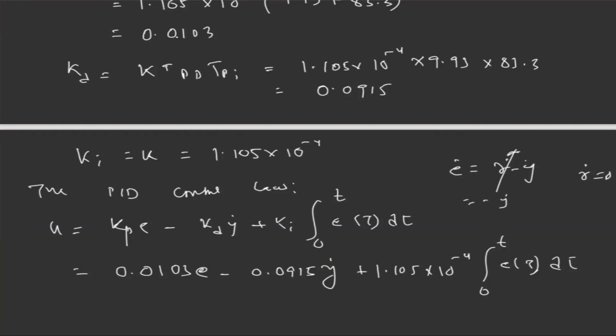So this is how we can design the PID control for the aircraft system in the frequency domain. But if you find from the simulation that the desired control system is not able to fulfill the mission objective, then what you can do is change the phase margin and increase the gain crossover frequency, and we can get our desired response. So this is how we design the PID control using the frequency domain in classical controls.